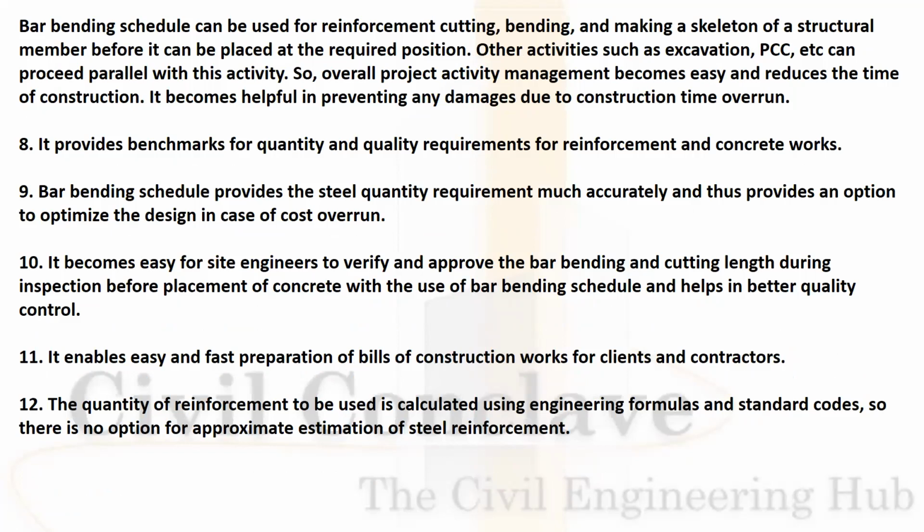Bar bending schedule can be used for reinforcement cutting, bending, and making a skeleton of structural members. Other activities such as excavation and PCC can proceed parallelly with this activity. So overall project activity becomes easier and reduces the time of construction.